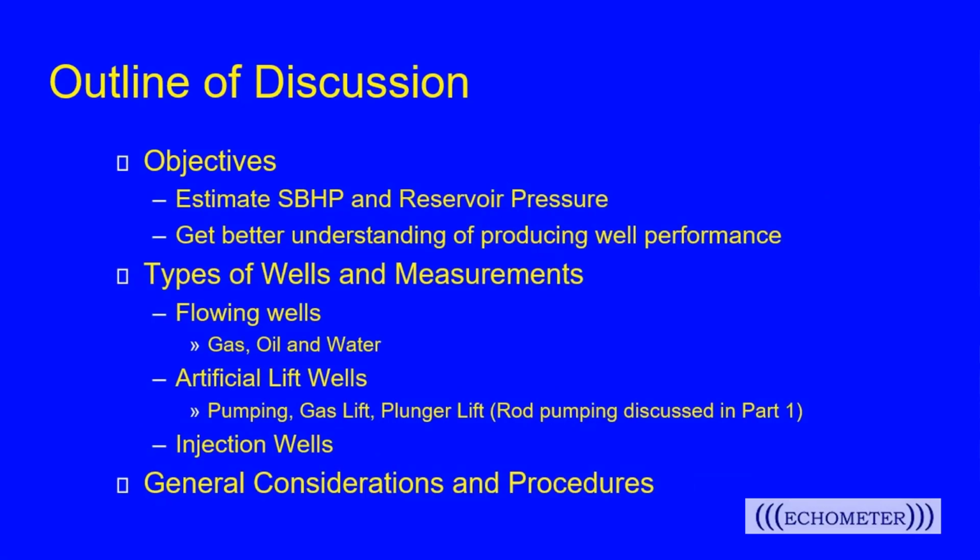But one of the things is we'll talk about coming up with a static bottom hole pressure or reservoir pressure and why that's relevant and why that will give us a better understanding of the producing well's performance. There's different ways to do this on different types of wells, and today we're concentrating on wells that would be calculated as a flowing well. So that would be, say, a flowing gas well. But also kind of under that same scenario would be a gas lift well, because you're still, in essence, flowing up the tubing, or even a plunger lift well.